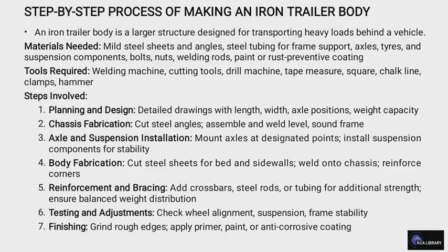The steps include planning and design and chassis fabrication, just like the tire truck. Then also the axle and suspension installation, where you mount the axle at designated points and install the suspension components for stability.